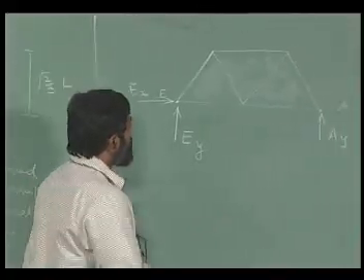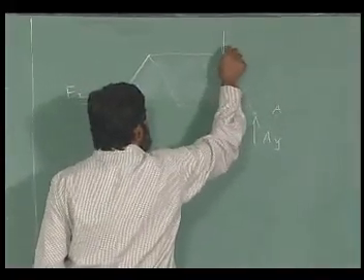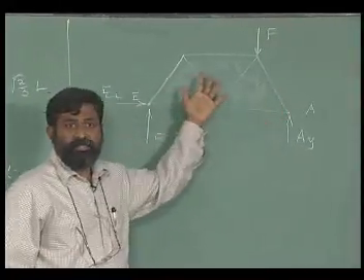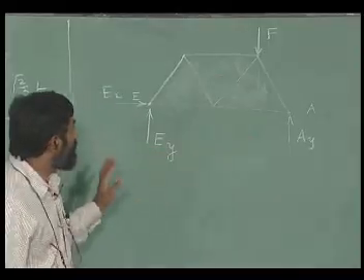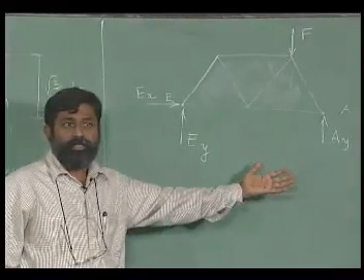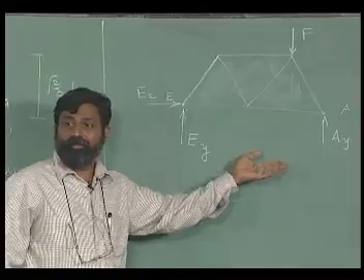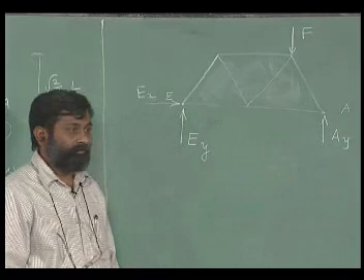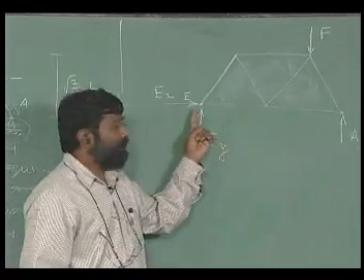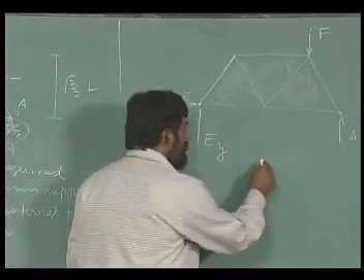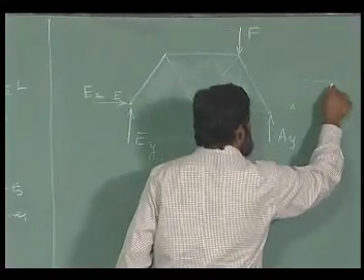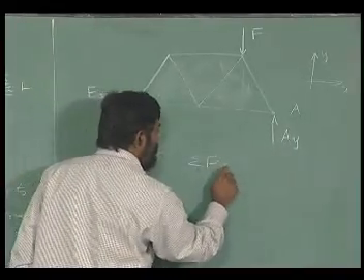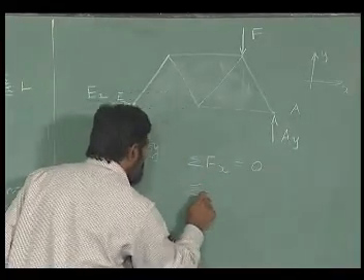Okay. Now I will insert the external force on this. This is the external force. I do not bother about anything else inside. There are no other forces acting, and this is a free body. I can always apply the equations of equilibrium. In this particular case, it is stationary, or a static equilibrium. Okay. So I can employ the three equations: sigma, let us say this is the x direction, this is the y direction. I can employ these three equations.